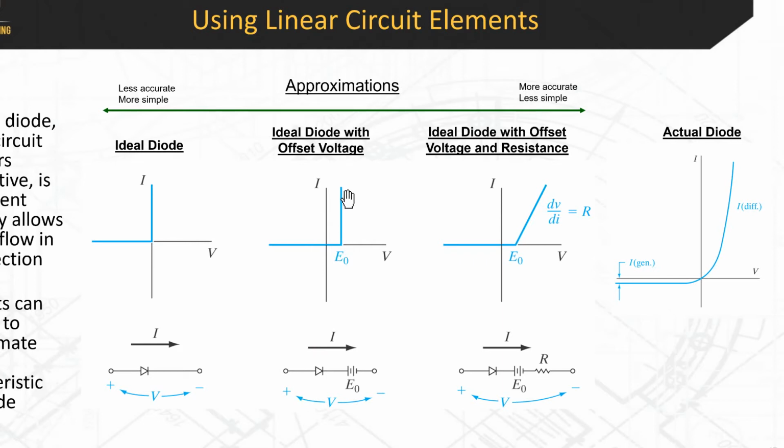All right. So I don't know if you've done LED type experiments or other diode circuits in lab. You can connect a voltage source to the diode, but if you do that, you have to be very careful that you don't go above 0.6 or 0.7 volts, because if you do, you'll get tons of current through the diode and you'll blow up the diode, right? So when you're thinking about it that way, like, hey, I can't put more than 0.6 or 0.7 volts across the diode, or else it'll just conduct current infinitely.